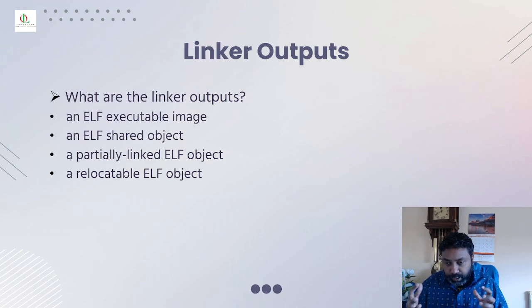The basic structure of the memory will have all the initialized and uninitialized data in flash and RAM, SRAM. So the sections will cover what's available in your project. If you write your program, the sections will tell you all about that project and that code. But as you learned yesterday, you can also customize the sections by writing your own ISR vector, which you learned in the previous session. You can also write your own linker scripts. By the end of this session, you will have a better understanding of how to write your own linker script.